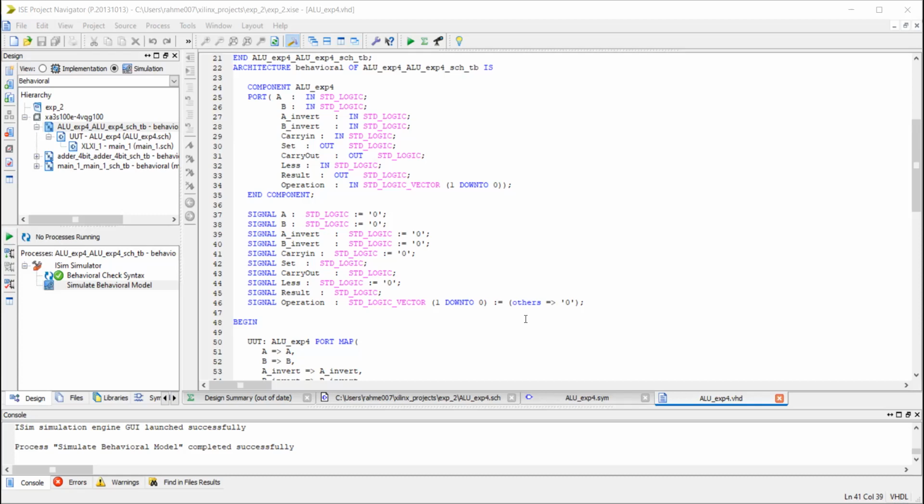In lab 3, you put four bits, but in here for the operation, as you know with the multiplexers, if you want to change the mode of operation, you need to have the operation bits. In our case, we have 4 types of operation. That's why you chose 2 bits for the operation, and that's why you have 1 down to 0, and we initialize them as 0, 0.